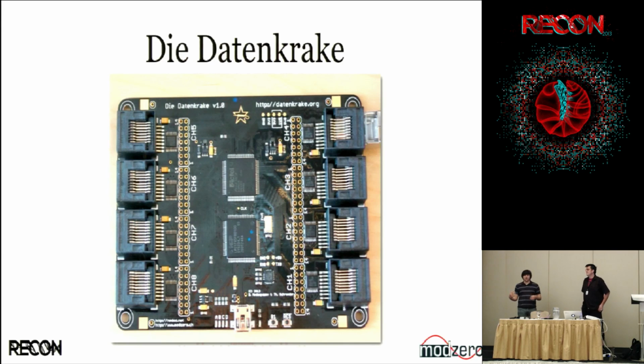You have 6 GPIO, and you also have VCC and ground, which means if you want to design a custom board, a little board that just connects over Ethernet, you can do it, and then you can do something crazy, do your own termination. I wouldn't do LVDS. I don't think the board's designed for super high speed stuff, but in general, you can design custom adapter boards.